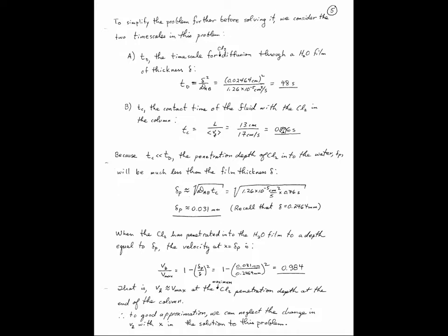So look at the picture here. The water is flowing down the wall of the column. It's in that column less than 1 second. It takes almost a minute for chlorine to completely saturate that liquid layer by diffusion. So there's a large separation in these time scales.